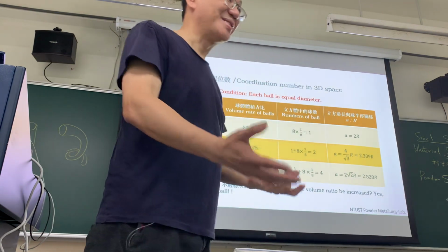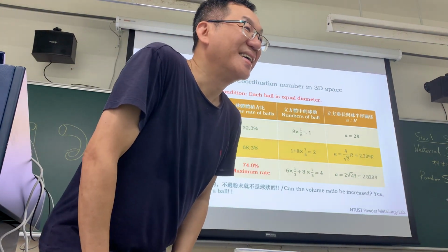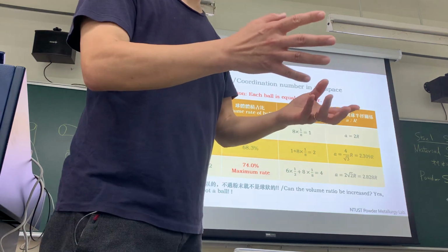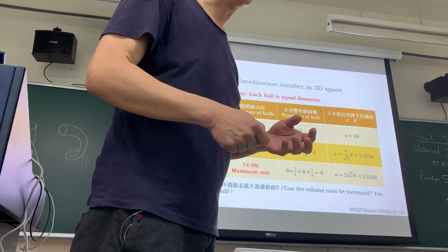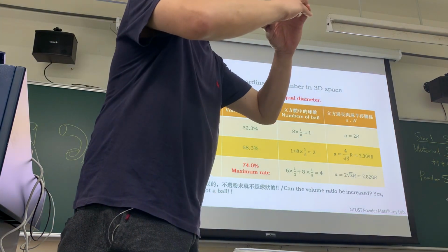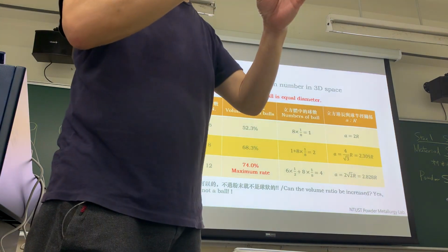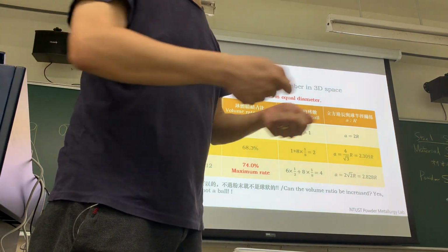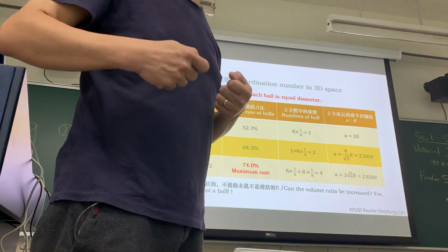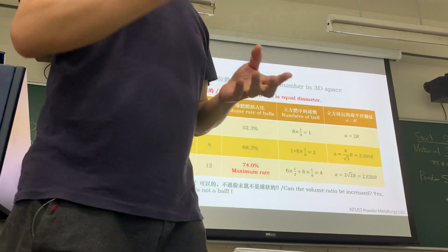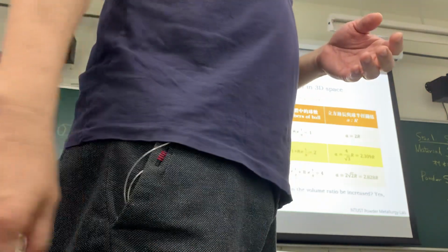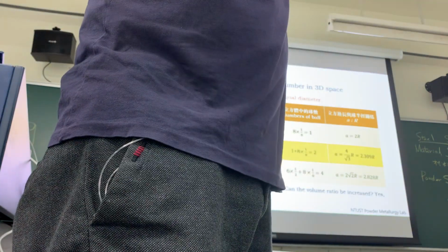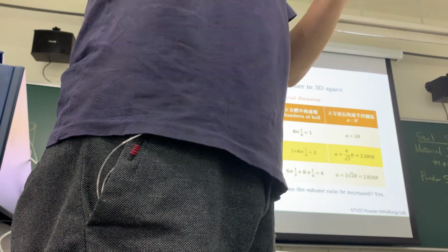Because you need more processing to mesh it, to inspect it, to check it. Everyone should be the same dimension, so every piece you need to know. You need machining, a mesh, and to check again. So random powder is cheaper, and uniform powder is very expensive. When your dimension tolerance is small, the cost will be higher and higher. Okay, remember.